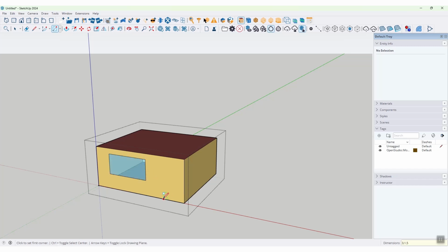In OpenStudio, windows and doors are usually sub-elements of a main surface. In other words, a window must be placed on a wall, and a door must also be associated with its corresponding wall. If the surface you draw is completely inside the wall surface, it is recognized as a window by default. Next, we draw a door on one of the walls.